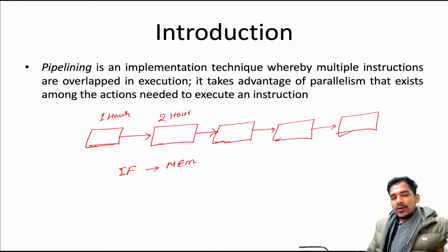And then we will talk about instruction decode. In this particular stage we are decoding the instruction. For that we are using the decoder, or we can say control unit. Then in the next stage we will fetch the operands. It is possible that operands are in the memory, so in this case we will also have to access the main memory. Then you will execute the instructions, which are ALU or load store instructions or some branch instructions.